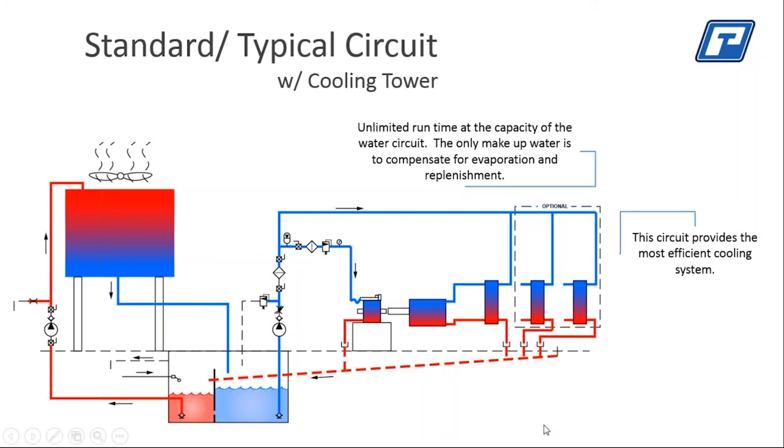As a matter of fact, you can see down in this, my cursor is looking at the hot side. This line coming in is a line leading from the water utility, and this is a float valve here. As the reservoir goes down because of evaporation or through parasitic loss, which we'll talk about later, this will replenish the system. So you have to replenish about 2.5%.